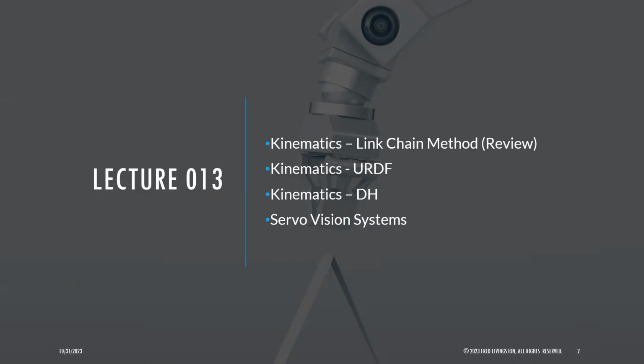Where things started was back in the days of DH, which is one of the more complex ones, but I'll show you that so you have exposure to it. They have a modified DH and an original DH. I used the original, and some professors use the modified, so the configuration is slightly different, but it all works together. At the end of the day, that 4x4 matrix, with its rotation and translation components, is going to be identical whatever method you use. It's going to be the same answer.